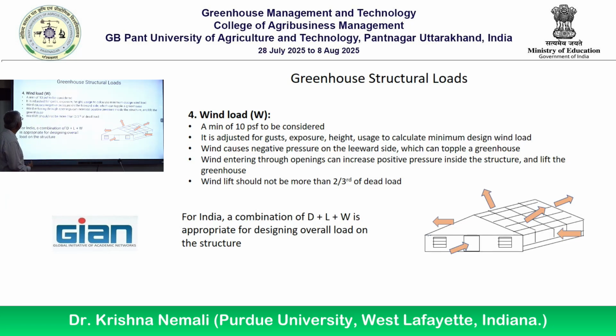Okay? And so for wind, we add another 10 psf at a minimum. The 10 psf will take care of 70 to 80 kilometers per hour winds also. The structure can hold it. So altogether, dead load, I said 5 psf. Live load 15 minimum.